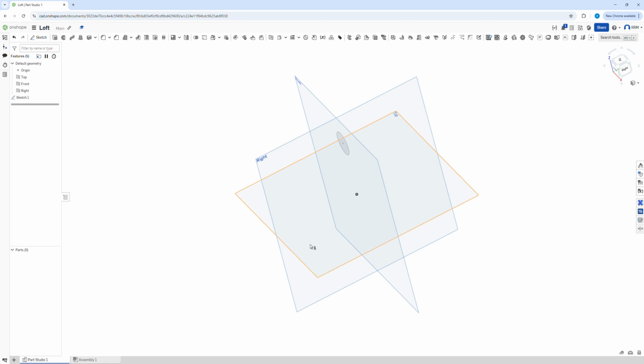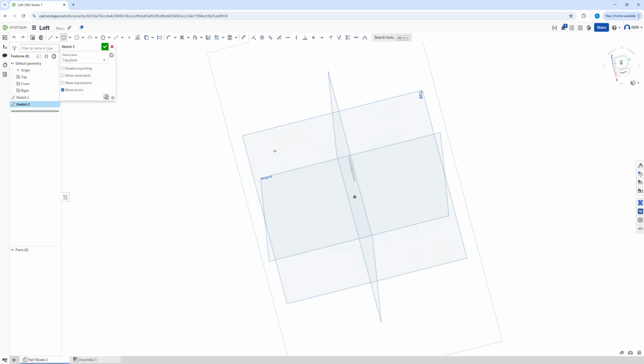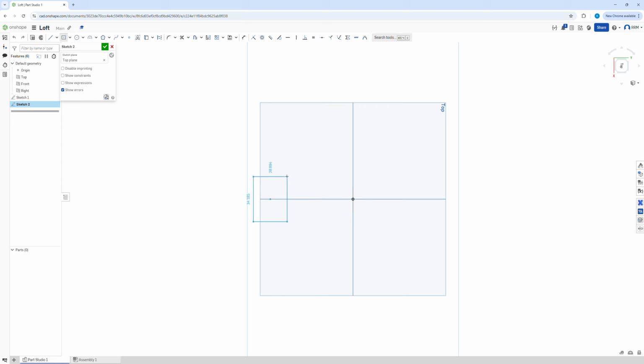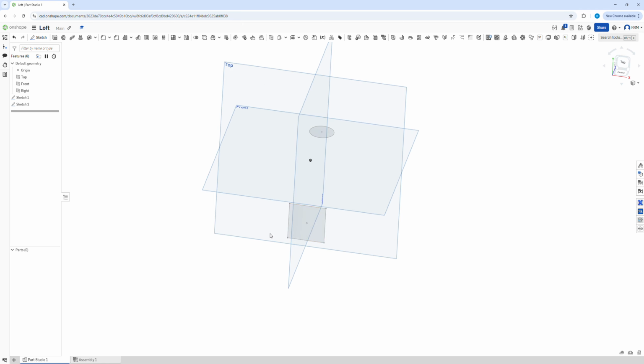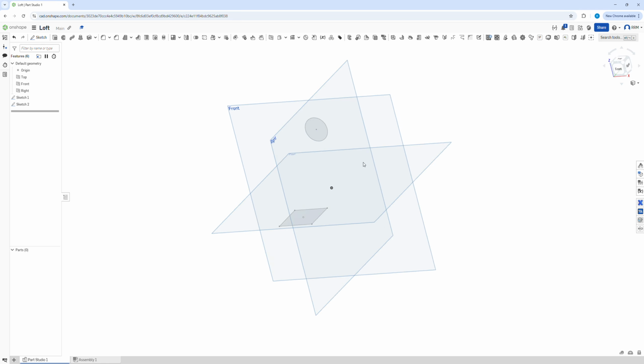We're now going to add one onto this top plane. I'm going to go sketch, and I'm going to take a rectangle this time, make it normal to, and sketch on here like so. Let's make this a little bit smaller, say 30 by 30, like this. It's obviously blue at the moment. We want to make this a certain distance from here, so let's call that 55 for ease. It's now black, it's not going to move anywhere. We can see that those two are aligned in terms of this origin point here and here along this right plane, and that's quite important.